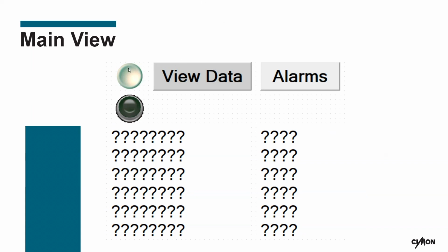So we have two buttons at the top left. Those are switch lamps, right? So I create a button where I can toggle a value on and off, or I create a momentary button where when I click on it, it holds it down, and when I let go, it makes the Boolean tag false. Or you can have it vice versa, it doesn't matter. Basically, the value is only changed as long as you're interacting with the button. It's not like a toggle that retains the state after you let go.